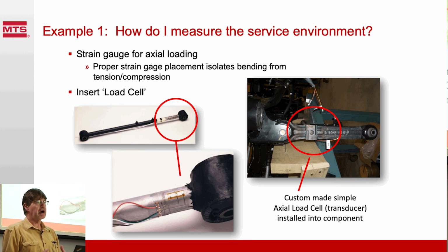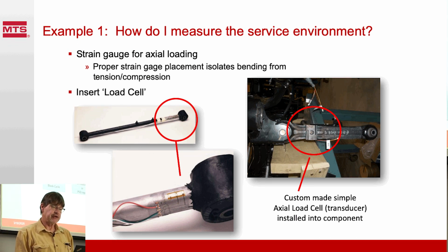So as a result, we had to modify it. We had to weaken it. We had to increase the strain and put specific points in there that we could measure at much finer resolution to resolve the loads. Now we have to be careful when we modify parts that we know what we're doing. We're not changing the dynamic response of the part. We're not increasing the risk of safety problems. Those things all need to be considered.